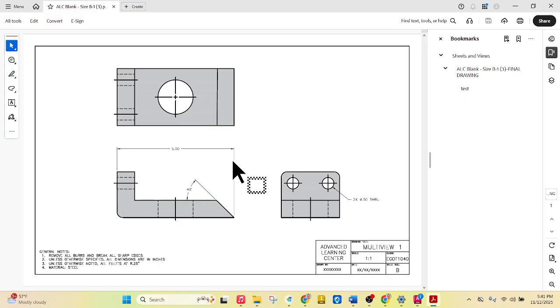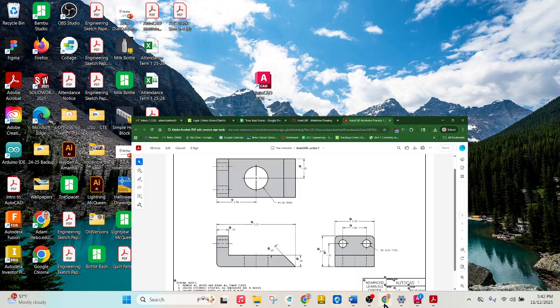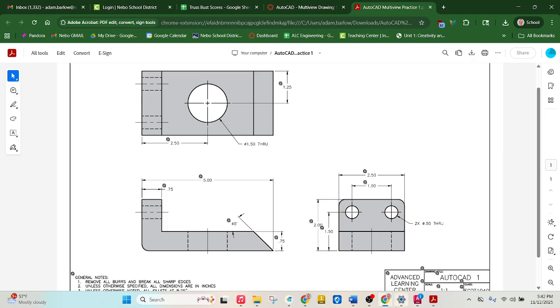And that looks pretty good, except I do have one error here. And you might be wondering, like, well, that looks fine, what's wrong? And it's this. So see how these lines on my center marks are all really thickly drawn? It's the same thickness as my object line, so that is a mistake, and it's a common one. And it's easy to miss that if I don't check.